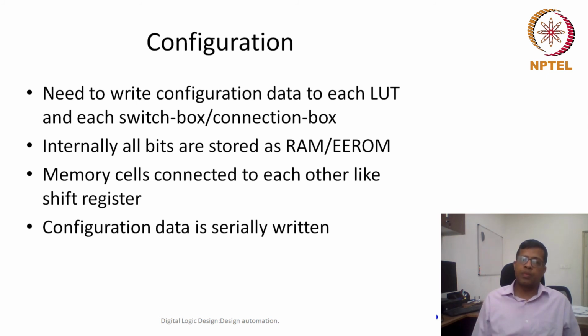To program all of them effectively, internally all of these memory cells are connected to each other. Let's say there are thousands of CLBs; each CLB memory location is connected to another CLB memory location in a serial in, serial out fashion. So it's internally a serial-in shift register.